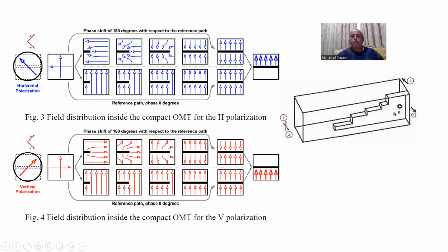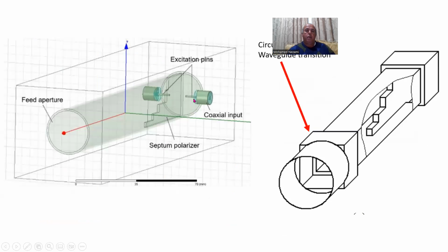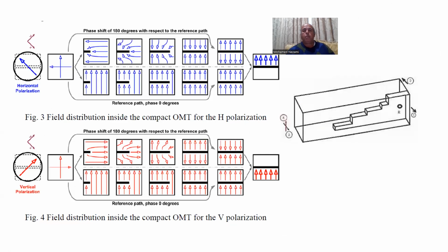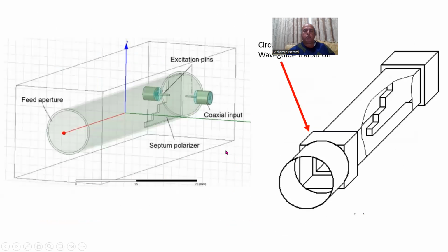Now, a lot of times, how do we pick the signal from here? So we have the feed in here, for instance, we have the horn and we have the dish in here. Signal comes in, and the back end is two waveguides. Now you can short them, okay, and place a pin to coaxial transition, or you can leave them open. You leave them open and then attach a waveguide flange in here. So depending on how you want it, that's a different way of doing it, okay?